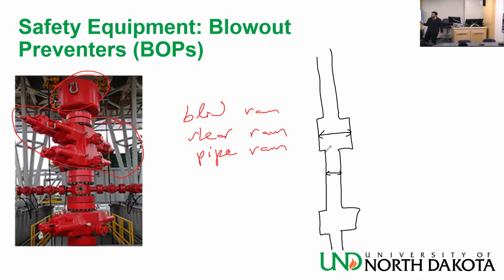This is the reason why, when they shut the well, they generally raise the drill string until they see a tool joint right here above the BOP. If you see a tool joint here, the next one is located 30 feet below. That means you don't have anything inside. There is also another reason why they raise the drill string. You don't want the bit to be touching the bottom when you shut the well, because then you might get stuck. So you want to lift it.